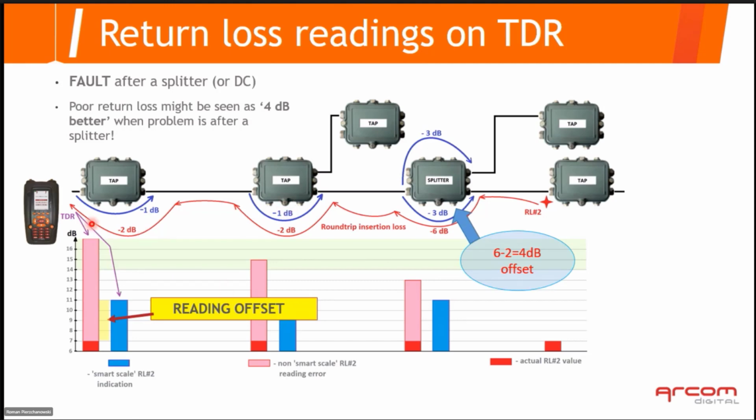With a traditional one, you would dismantle everything and you would TDR it from one device, and there would be no ambiguity in what is what, whether it's behind me or in front of me. You will find out how to recognize this. You can also verify on a splitter by connecting to the other side of the ports with this meter in TDR mode and ranging the impairment.